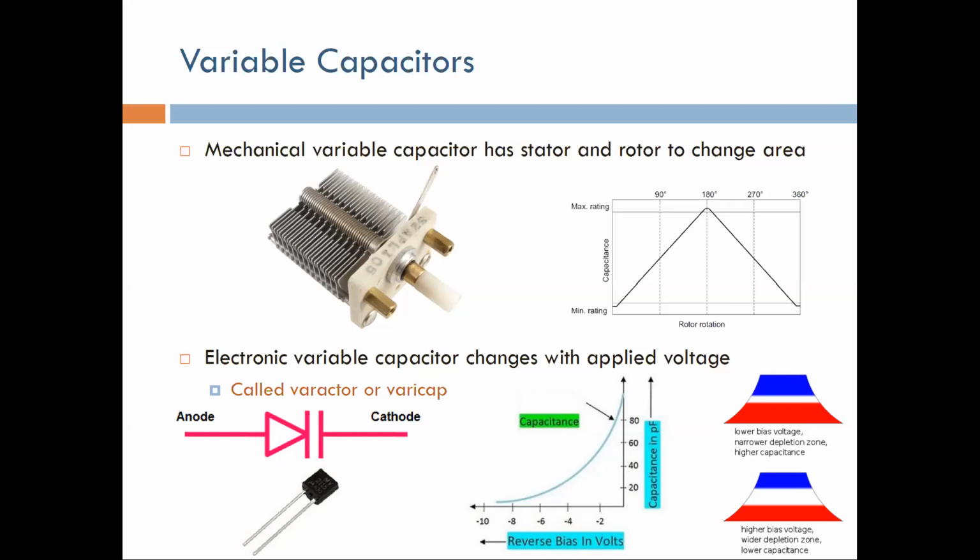It's very easy to generate it using software. You generate a particular voltage using software in a microprocessor or microcontroller, and feed that to this component, the varactor, and this will change the tuning of the tuning circuit that the varactor is used for. So it's very easy to do that with software rather than having a mechanical knob moved or something like that.